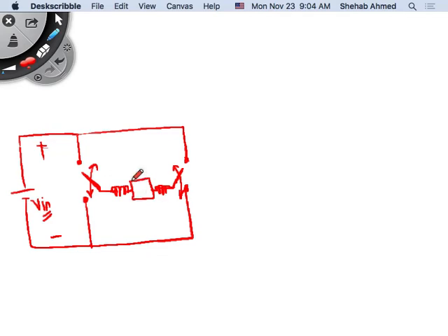This load can be a resistive load, so there's an inductor here, and then I can draw a resistor here, and maybe I put a capacitor as well, or maybe not. Whether or not I put a capacitor will depend on how much ripple voltage I want to maintain across my load. So it's up to us later to decide if you put a capacitor or not.